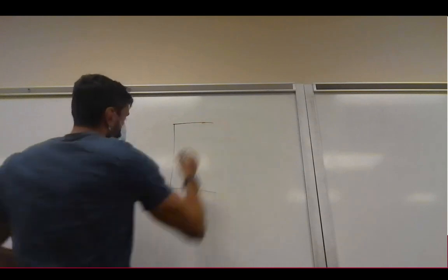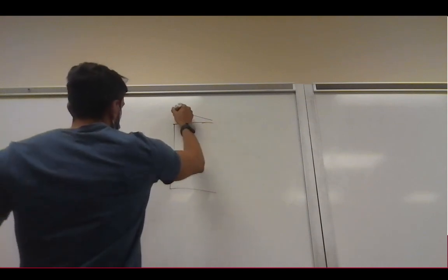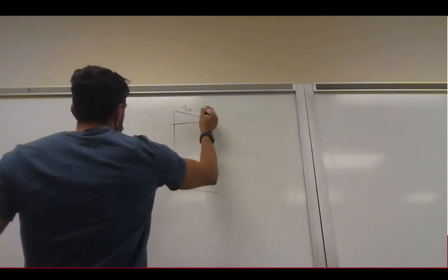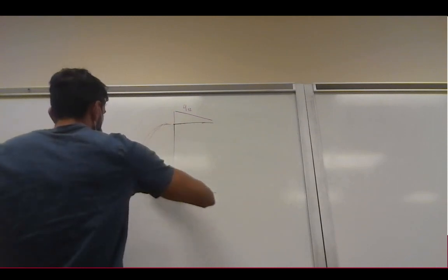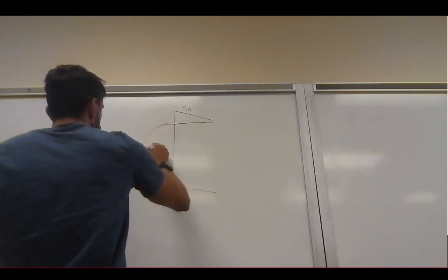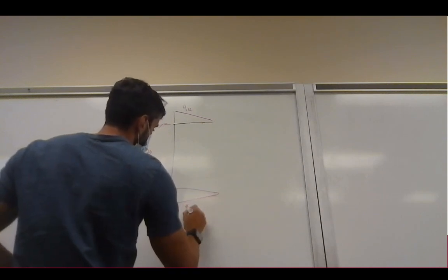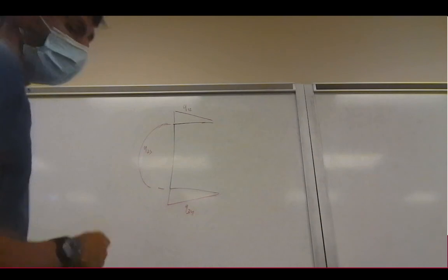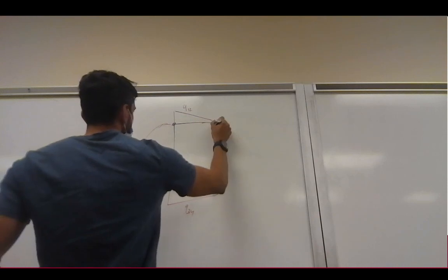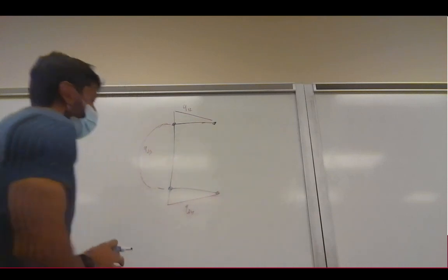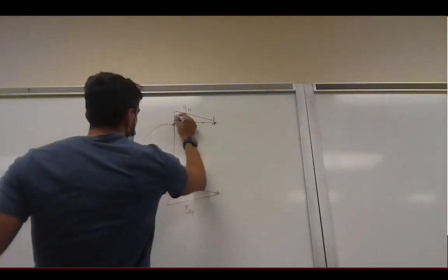if we calculate our shear flows, say with red, we'll get something like this. This will be our q12. We'll go in this manner. This will be q23 and q34. So this is our non-idealized section, and if we have an idealized problem, then basically we would have 4 booms here at these locations, and we say the shear flow changes when we cross a boom. So once we cross this boom, we have a constant shear flow.